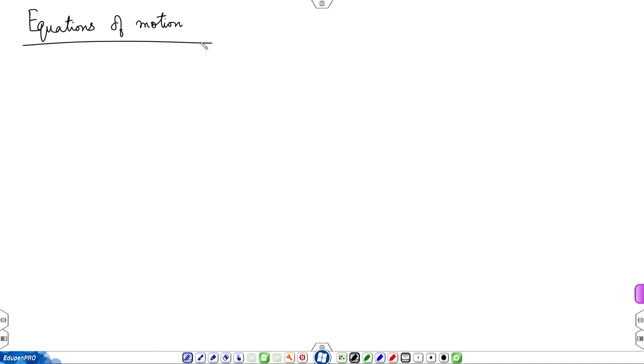So, pressure at a point, when you determine pressure at a point, it is an example of local solution, obtaining a detailed solution. So, pressure is a local variable. When you integrate pressure and get a force, it is a single force for the entire, let us say, gate or surface or the object being studied.